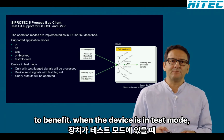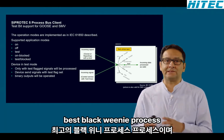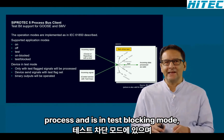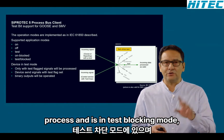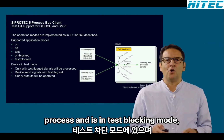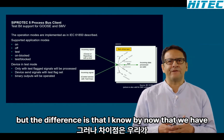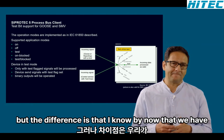When the device is in test mode, only signals with test flag will be processed. The device sends signals with a test flag set, and the binary outputs will be operated. The other option is, if the device is in test blocked mode, only signals with test flag will be processed, but the difference is that no binary outputs will be operated. Okay?